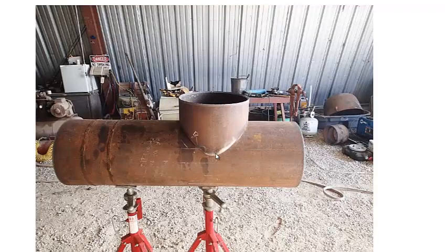Yeah, here's like another one. These are same diameter pipes, only they've rounded this off and they're kind of lining up their IDs, and they actually do the development on the branch. They drop it onto the header, and they use the ID of that branch to lay out the header. They kind of mark the ID and OD of the branch, and so that's kind of a different way to do that. And it'll look just a little bit different than how we'll draw it, but I just wanted to point that out.